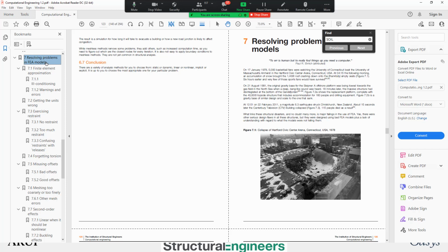To be honest, for most designs you should probably do the analysis two ways anyway. So even if you're doing an FE analysis, I would probably do a yield line analysis on the side just to make sure they're giving similar results. How appropriate yield line analysis is, how valid it is, is something I have doubts about, but I'm not qualified to state anything. A lot of people are very keen on it, and I'm sure they know what they're talking about.